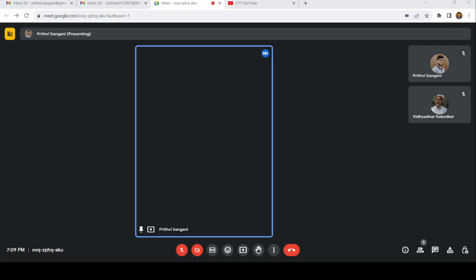So I'm applying the redundant force, which we mentioned as HC. Let me write it as HC. And we need to find the displacement. We will get some displacement, this is delta 2. How do we find the displacement? Again, it is quite similar. For HC, we'll find the internal forces, and also we'll apply a unit load of 1 kilonewton in the same direction to find our internal forces.